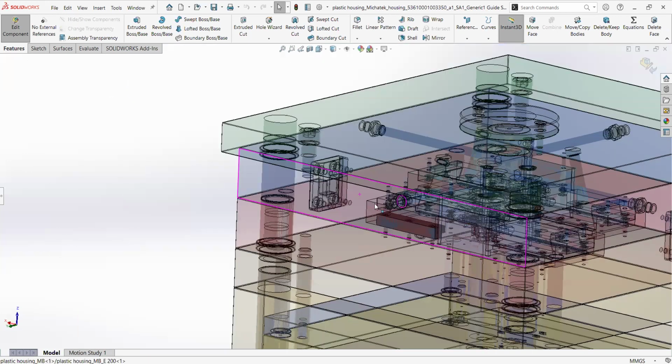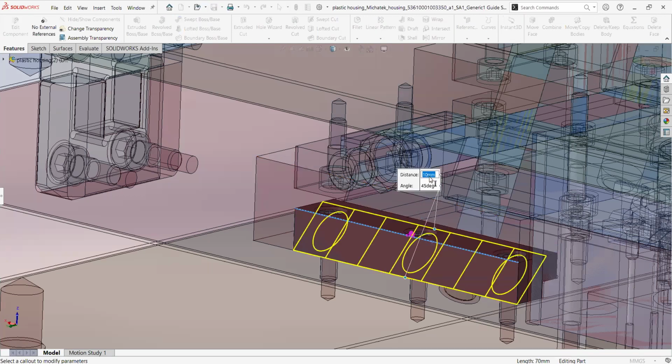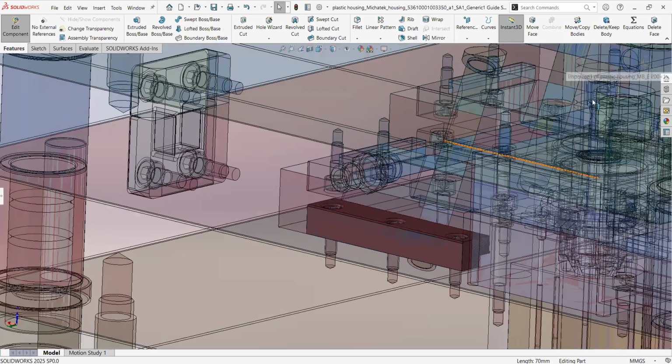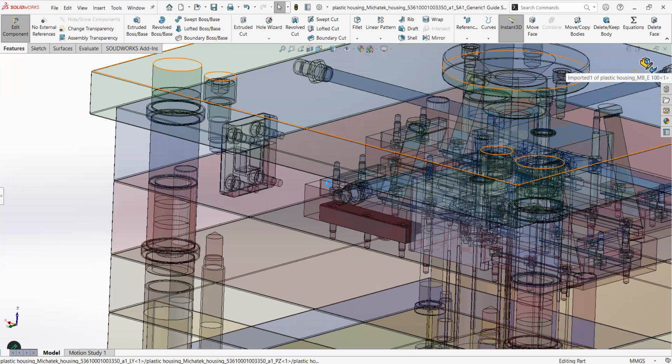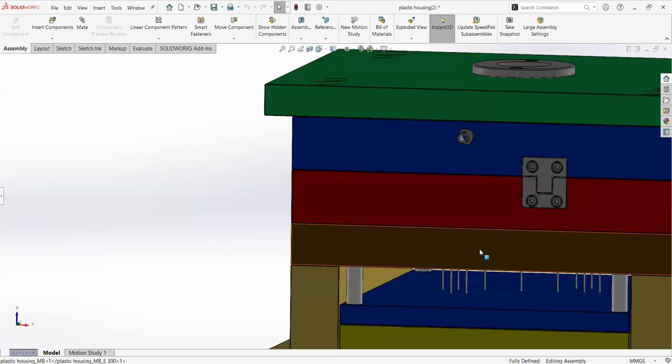More operations. So let's do something here like a chamfer. There you go. So let's say it's going to be a 0.5 chamfer. It's very tiny. I have here the check to finalize the thing. And then I can just click in this icon at the right top to jump out of the editing of the part.